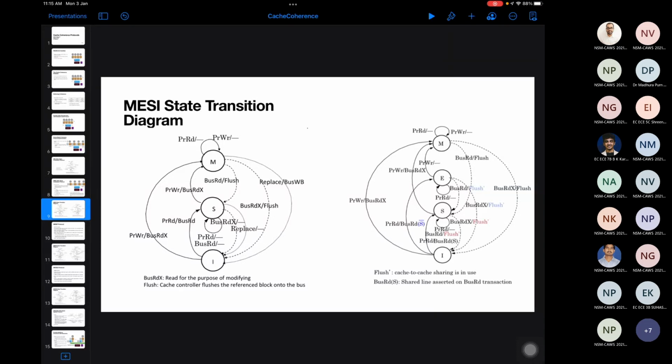Okay, but do we have that? For example, if you see the state transition diagram, there is a cache to cache transfer. But now how do we decide whether it is core 1, core 2, or core 3? Because everyone is trying to place the data on the bus. Now there is a bus arbitration logic, and someone has to win the arbitration. There is another overhead if more than one core is there. Also, if there is no cache to cache transfer, then what is going to happen is that the LLC is always going to supply the data.